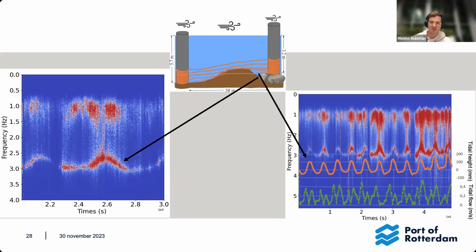Oh, that's a good question. I only have very preliminary results on that, which I haven't really shared yet. But it's true, these companies, for instance, where I also measured this export cable from, they have these DTS measurements, usually Brillouin, not Raman, which was also new for me. And when we compare our results, we see many striking similarities, but also sometimes not.